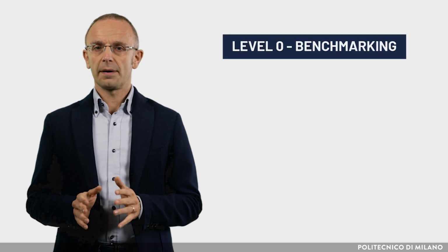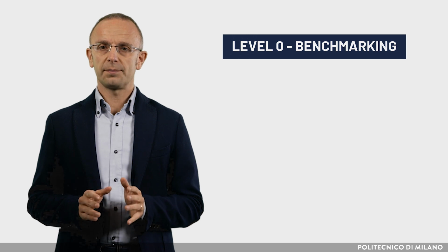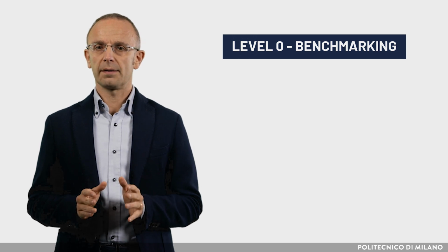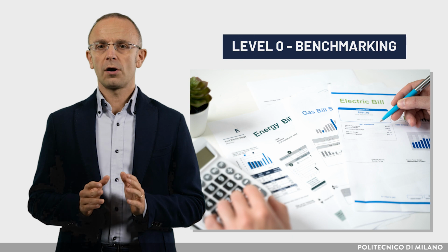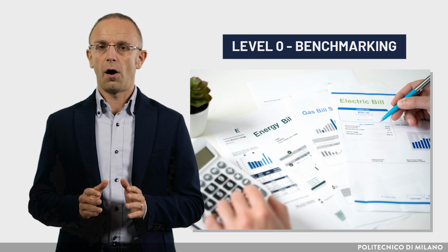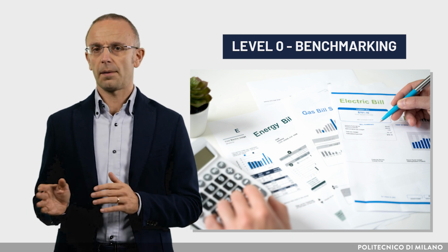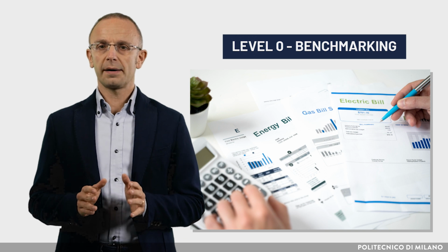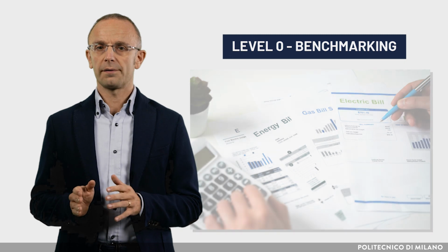Generally, 4 levels of analysis can be outlined. Level 0, benchmarking. It is based on the assessment of the historic utility bills and costs and on the comparison of the performances of the building to that of similar buildings. This benchmarking allows determining if additional analysis is required.